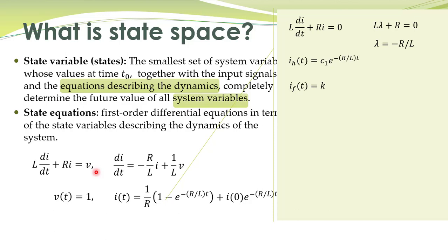भूल चुके हैं सारी बातें differential equations की. So you have this constant input and you assume some constant solution and then substitute this solution into this equation over here. That is the procedure. So derivative of this constant with respect to time is 0, so that gives you k to be equal to 1 over r. So this is the forced solution, and this is the homogeneous solution.